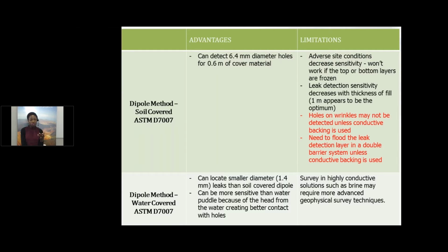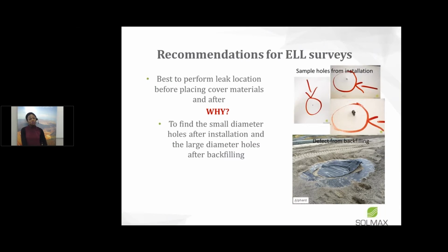So a few recommendations now. Which one do we perform? Do we do leak location before backfilling or after backfilling? The recommendation is to perform both. Do a leak location following installation to find all those tiny or smaller diameter, numerous leaks, and then do another one following backfill to find the fewer, larger diameter leaks.